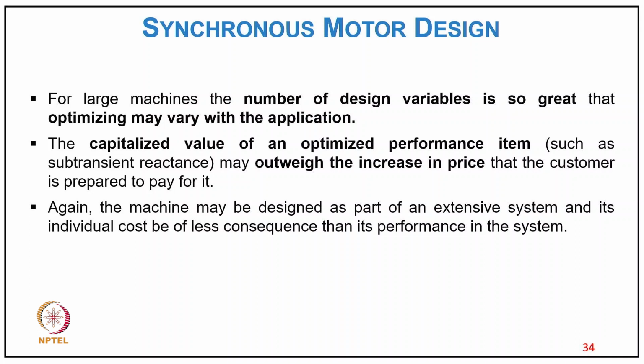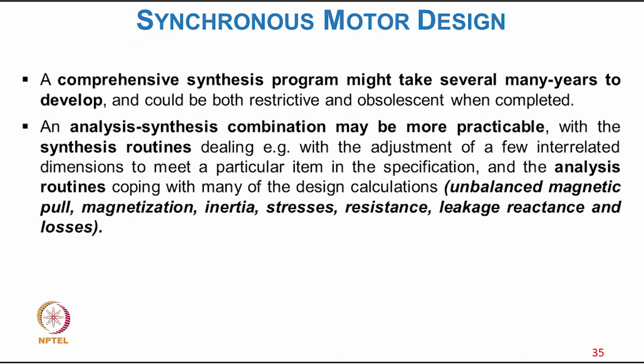And again, the machine may be designed as a part of an extensive system, or its individual cost may be of less consequence than its performance in the system. A comprehensive synthesis program might take many years to develop and could be both restrictive and obsolete when completed. An analysis-synthesis combination may be more practicable, with the synthesis routine dealing with the adjustment of key interrelated dimensions to meet a particular item in the specification, and the analysis routine coping with many of the design calculations: balance, magnetic pole, magnetization, inertia, stresses, resistance, leakage, reactance, and losses.